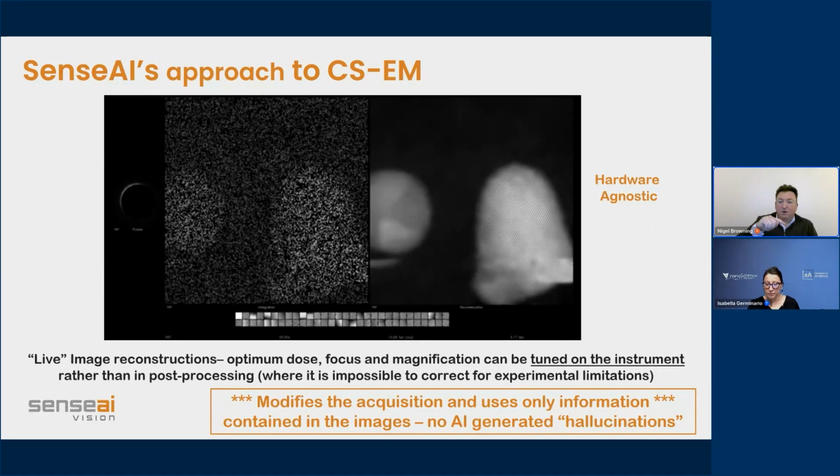So if you go with our random walk approach, what you're doing is sort of randomly scanning in that direction, but you're following in the direction that the scan has been designed to do. And that means that by only stepping one point up or down as a function of going left to right, you minimize the hysteresis in the scan. Now that works very well for the very fastest image,